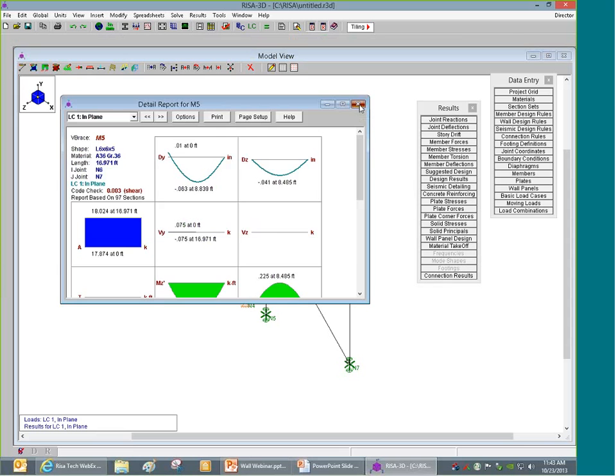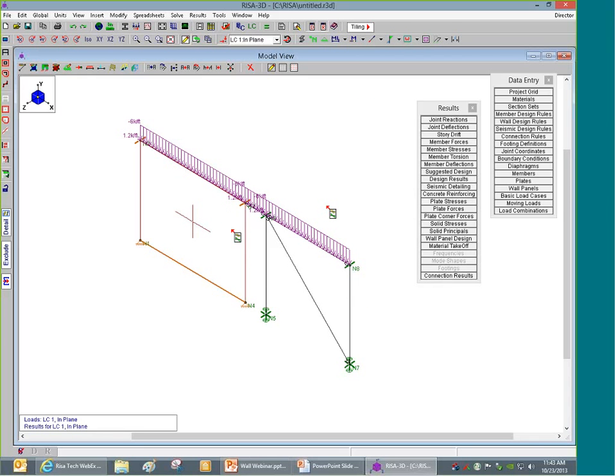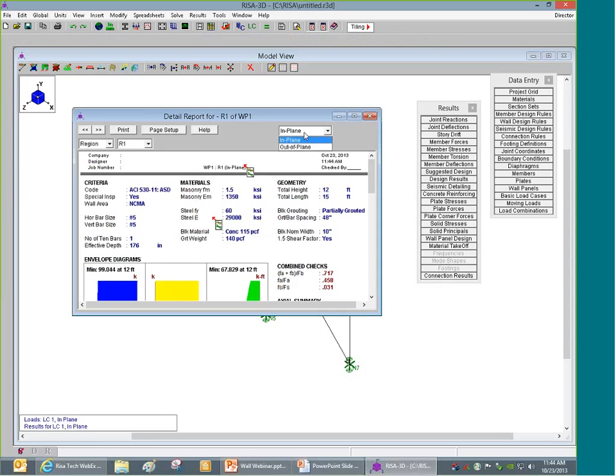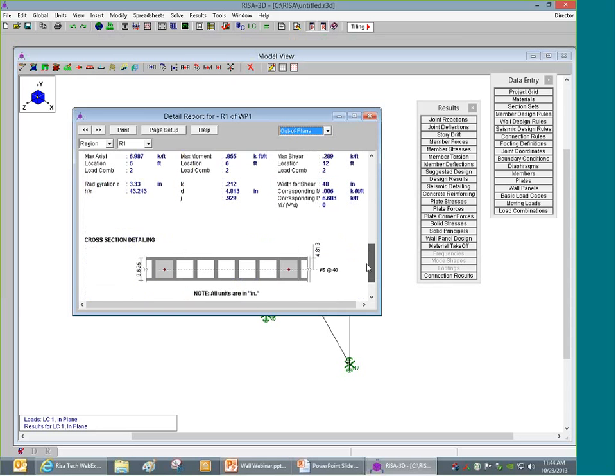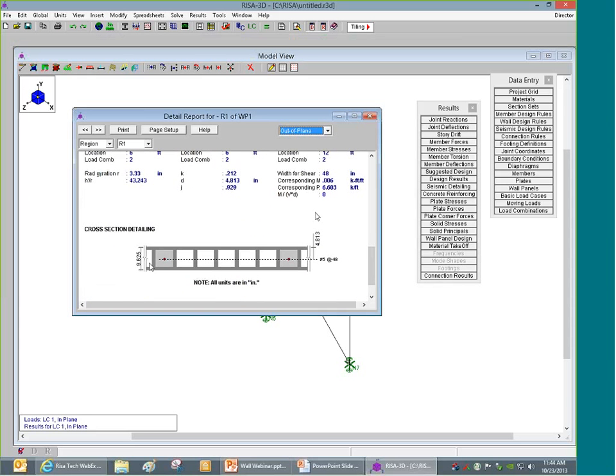And so in this case, we're saying, hey, the single angle can carry that 18 kips, which cuts down on the amount of force that's in this wall. And so you can see how just that difference between the rebar out of plane affecting how much the in-plane stiffness was, that was huge. That's a very big difference.